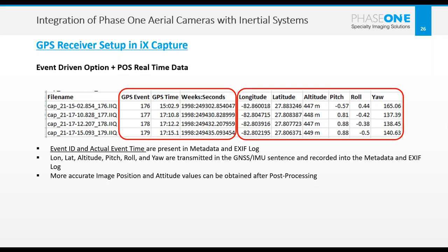They are still not post-processed values, but it helps in case during the processing workflow you may want to have the images geolocated, which is slightly different from saying that the images are georeferenced, which they are not. It's just a position tag, an attitude tag for ancillary purposes, but they do not represent an accurate position or an accurate attitude for photogrammetry purposes.